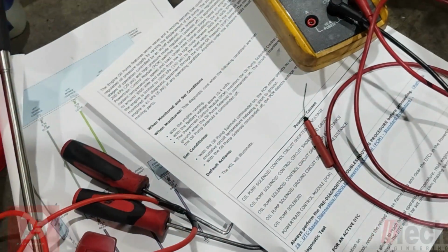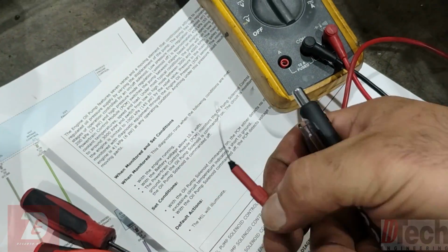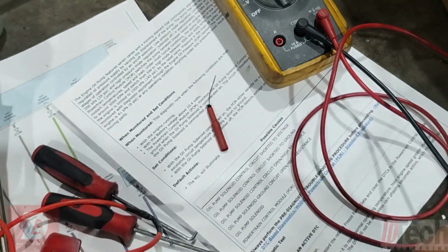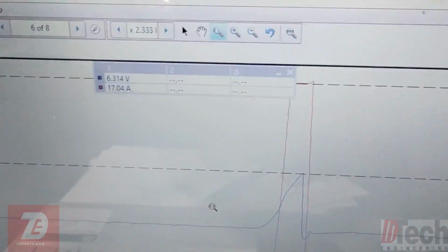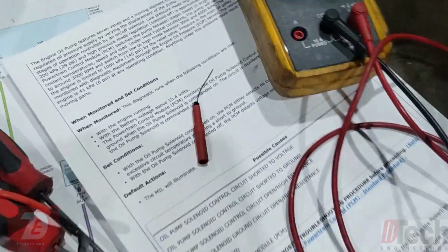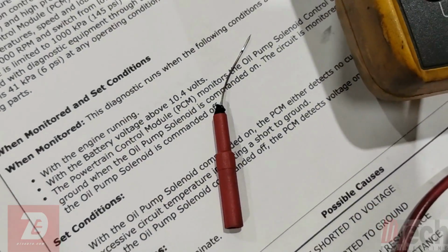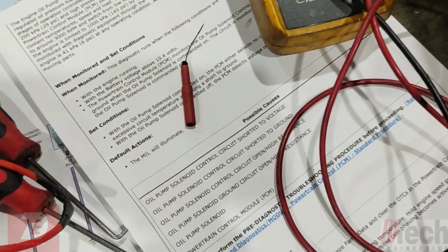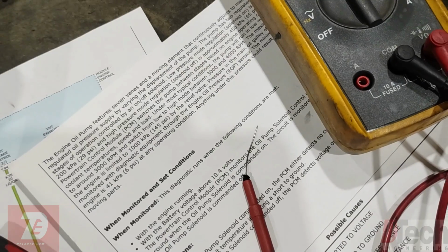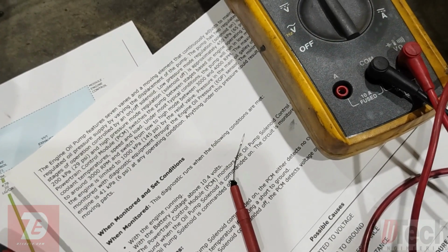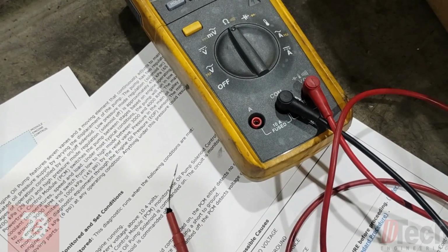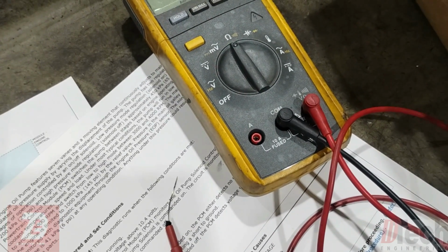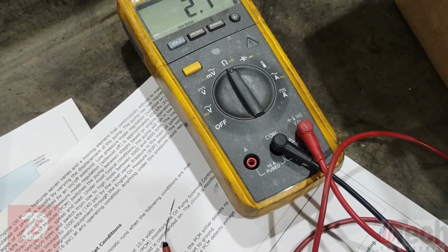I was going to say I wasn't expecting it, but based off the undeniable fact that we've got a measurable number, which is 17 amps, we can clearly see why that was a result. So I was attempting, while scoping and graphing, to just quickly tap and see if we get a better square wave, but we cannot because it's the same result.